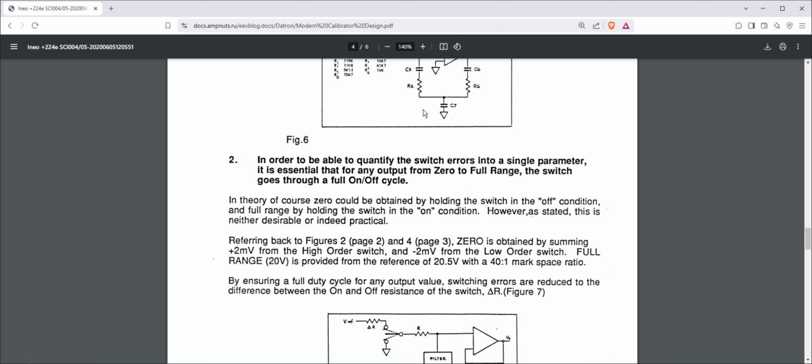This modification from the original scheme was not without a catch, since the readings were now significantly noisier. The INL plots looked so clean only because I'm averaging the INL over 10 independent runs, with each set point being tested in a random order to prevent correlation between successive steps.